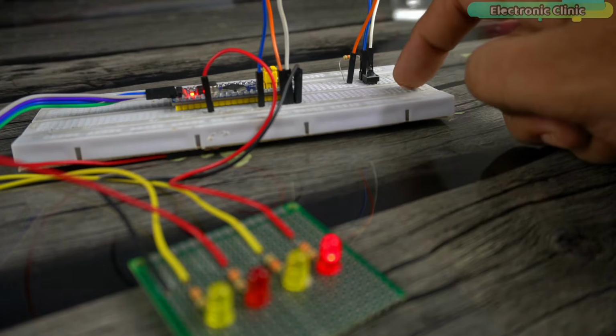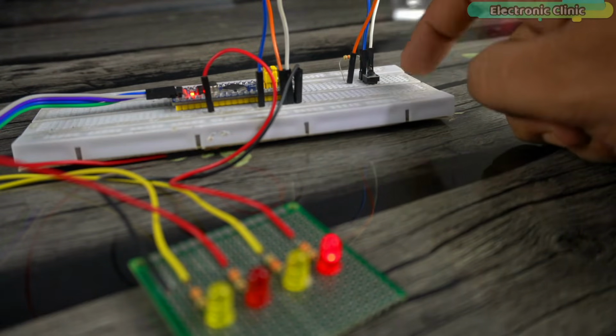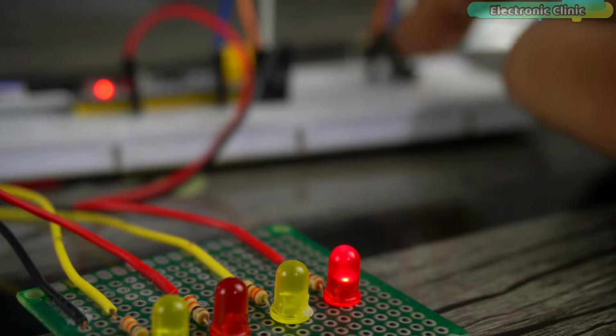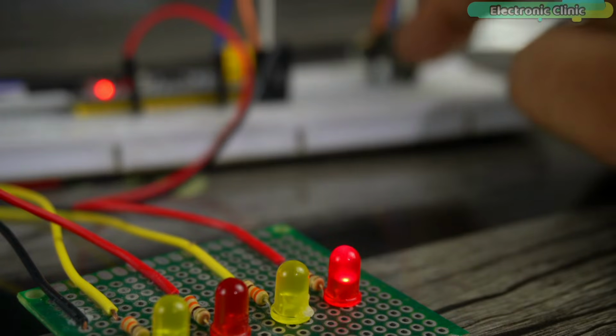You can see each time I press the button, the LED changes its state. You can replace this push button with a digital IR sensor and the LED with a relay to make a contactless AC or DC load control system. You can use any type of digital sensor. You can even convert this simple project into a security system using a digital PIR sensor. Anyway, in the next example, we are going to use I2C supported 16x2 LCD with the STM32.